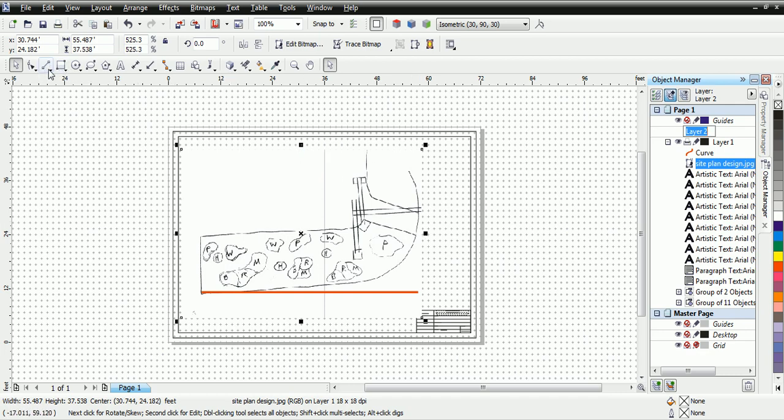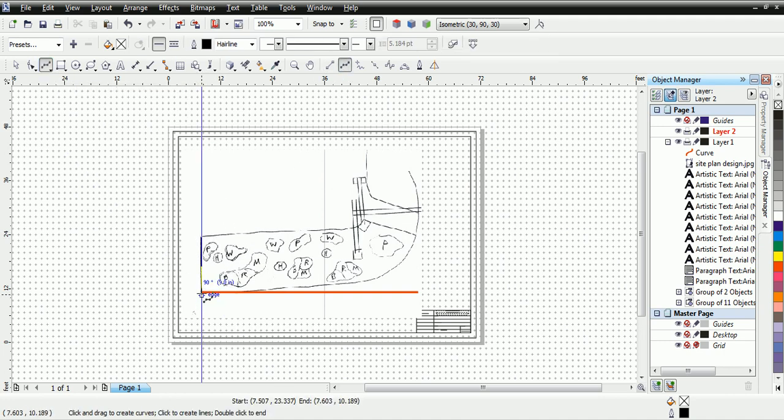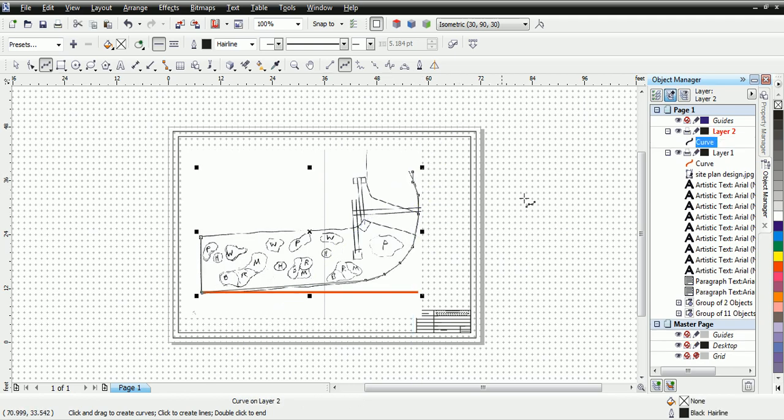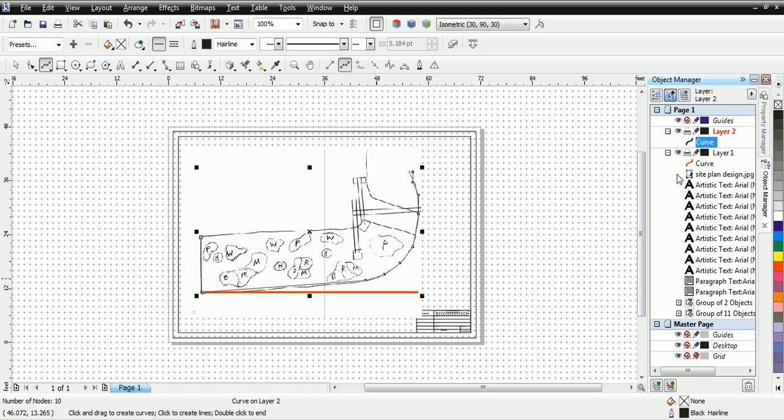For illustration purposes, I'll simply use my line tools and show you the effectiveness of using the layering. So if we wanted to turn off our first layer, you'll see that only the line on the new layer does appear. And I would suggest that you use a combination of your multi-point lines and then your B-spline tool to get that nice curve edge.